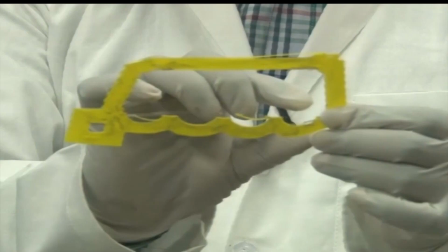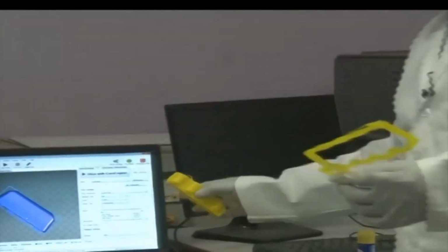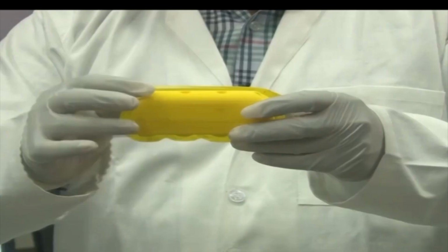So we are talking about the selection of brim here in the software. When the nozzle head starts printing, it is the actual model that we want to print, but it will deposit a little extra material to produce this first layer. This is actually the brim. Okay, this is the model that we have. This is the model that is produced. So it will deposit the material, a little more material.